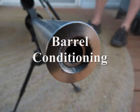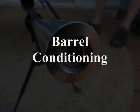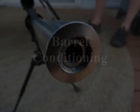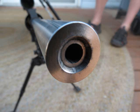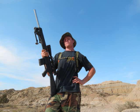There's another thing we want to talk about here real quick, and that's barrel conditioning. Basically, the temperature of the bore has a direct bearing on the developed muzzle velocity as well. And different metals have different properties at different temperatures, obviously. They expand at different rates. They become softer or harder, or the lubricity of the metals increases or decreases based on temperature. So this is something you want to be aware of as well. I just throw this in here. There's not a whole lot we can do about it besides just be aware of it, and then we can plot this out when we're recording all our muzzle velocity data. But it is something that can throw you off as well.